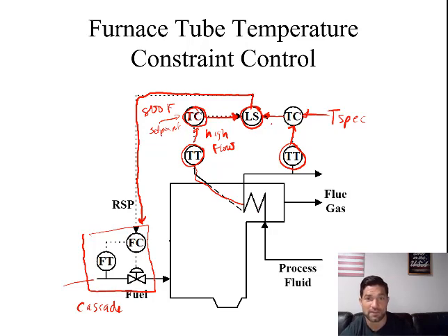So relatively, this would be a lower flow rate. Under normal operation, if this is at 400 degrees F, for example, this over here is going to be a low flow relative to the other set point. What that means is that if this is operating at 400 degrees, we can send in a much higher flow rate of fuel than we need to keep this temperature at our specified temperature value, right?